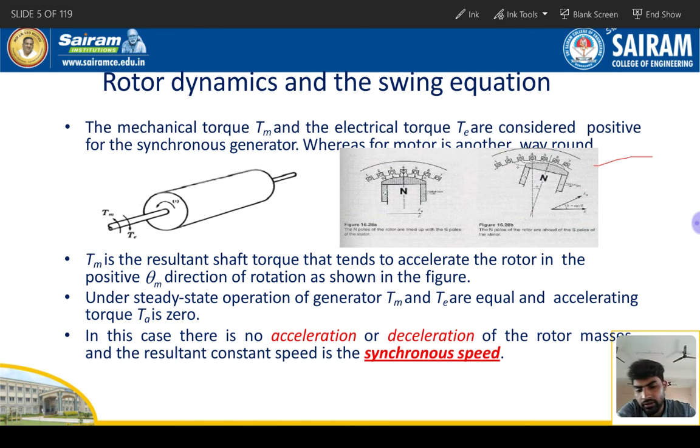So, mechanical torque we have T into omega, twisting force into omega. Omega is 2 pi n by 60. 2 pi is the circumferential displacement, circumference 2 pi r, and n is the rotation; 2 pi n by 60 is the displacement over the time taken, that is the angular velocity, displacement by time, right.